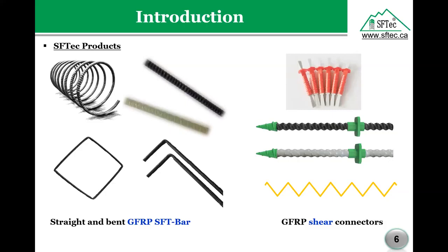So our products, we are capable of producing different types of FRP products. We produce FRP bars, spirals, connectors, bent bars, and whatever shapes you will need. The most popular, of course, of these products is definitely the bars. However, the most popular fiber is the glass out of the 3 listed before. And the reason being is that, as I explained before, it has already doubled or tripled the tensile strength of steel. However, it's the cheapest in terms of cost, in terms of budget, compared to carbon and aramid. So that's why GFRP glass fiber polymers are the most popular in the market today.